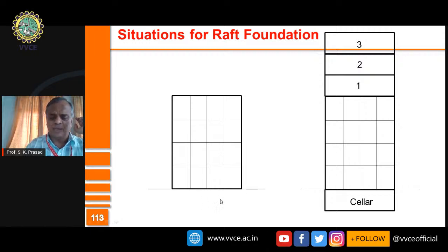And because you have removed 3 meters of soil, approximately over an area of 1 meter by 1 meter, 18 kilonewton is the load which is removed. And hence, you can add 3 floors, each of 18, which means, totally 54 kilonewton per meter squared is the additional area load which it can take. And hence, provide you with a situation where you have a stable building. Therefore, instead of maybe 4 floors, you are going to make it 8 floors, including 1 cellar.